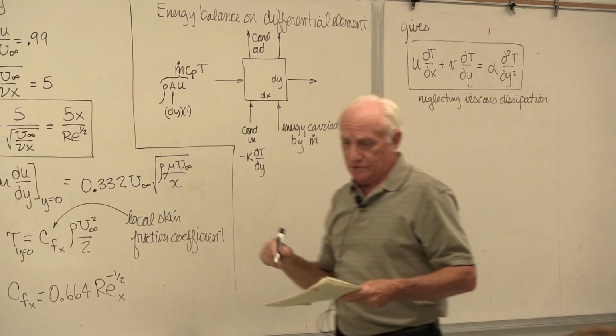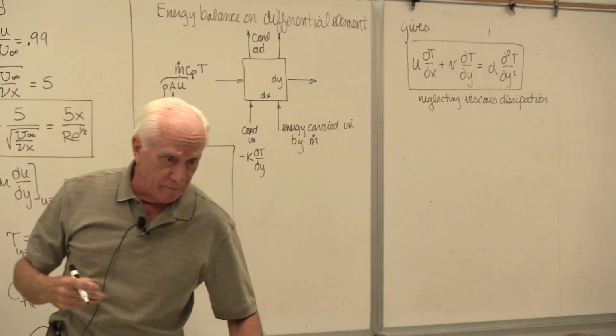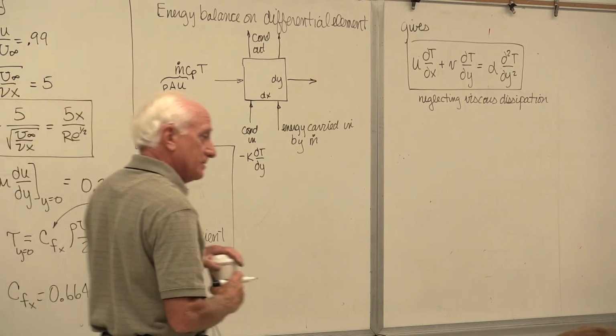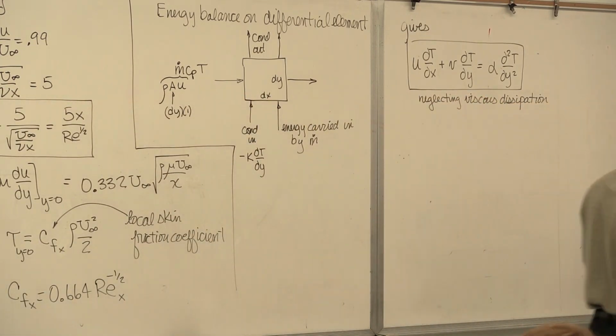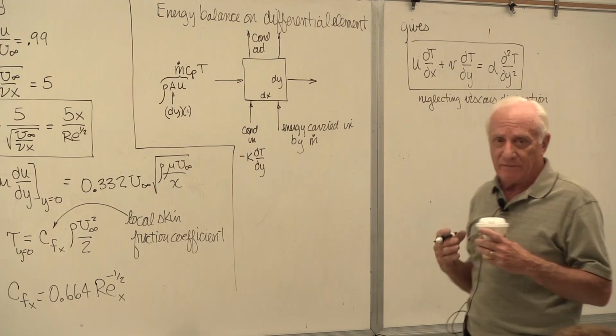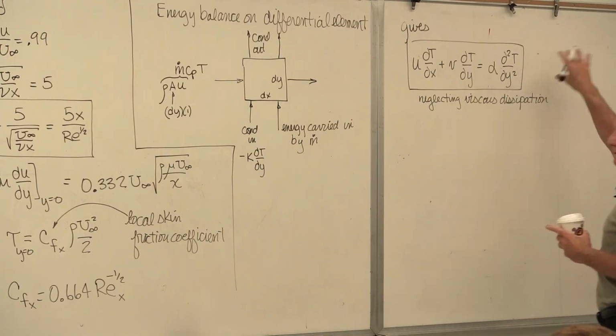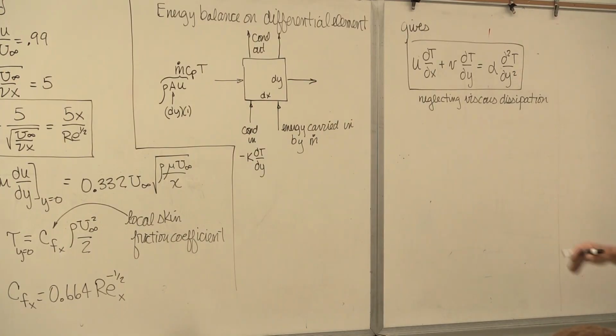And in that, there can also sometimes be energy generated by viscous heating effects. When a space shuttle, or any kind of manned spacecraft, comes in from outer space, you see this glowing light. There's a lot of heat being generated at the nose area of that vessel. But that's high-speed flow. This is not Mach number 5. This is fairly low-speed flow, so we're not going to worry about viscous dissipation. That term disappeared. It has mu in it.